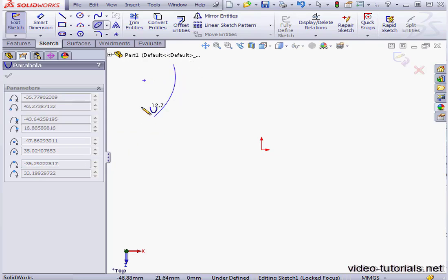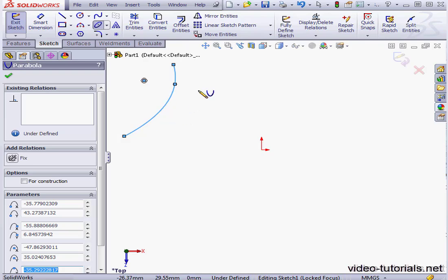Creating a parabola involves 4 steps, selecting a focus, vertex, then a start and end point. This approach makes it difficult to reference existing geometry, so that's where the Conic Curve tool comes in handy. It can be difficult to snap the end of a parabola to a line, for example, if you need to create tangency. Let me try an example.